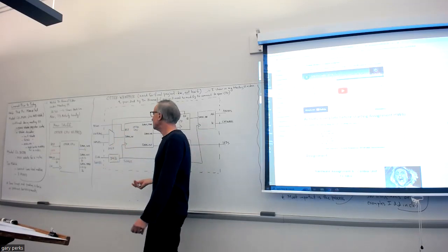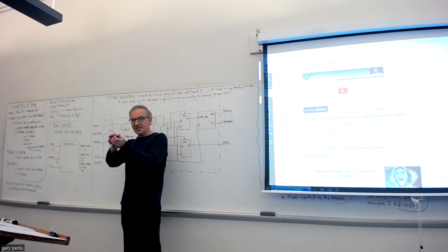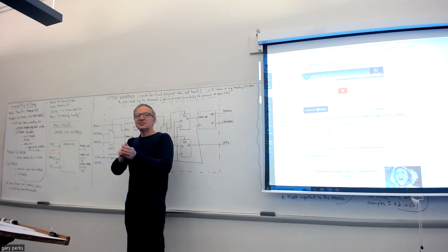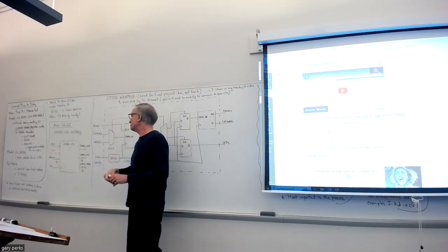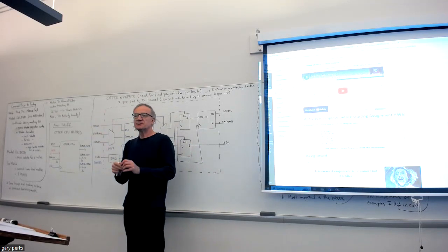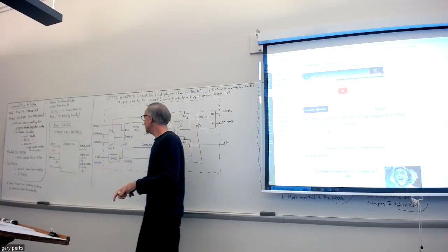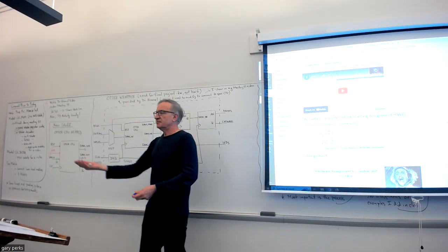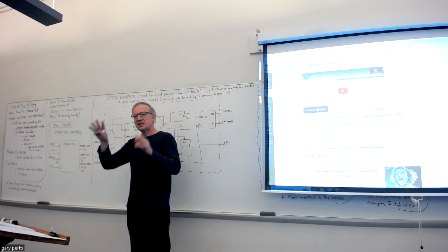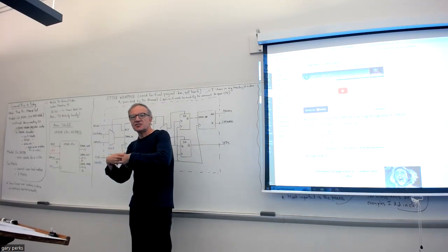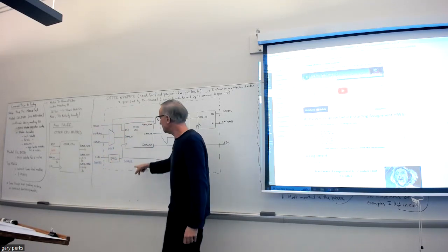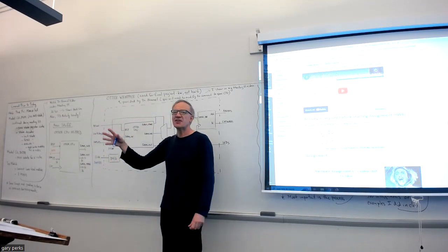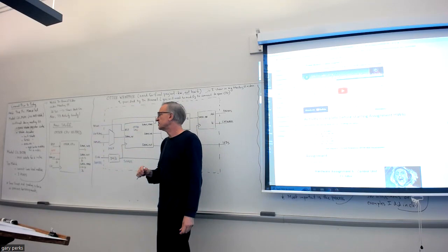There could be a possibility where if you run it at 100 megahertz, due to propagation delays, say in your execute state, maybe it wouldn't work quite right. But under that same situation, it could work with the slower clock. So again, this is just to give some margin of error, to provide some wiggle room.